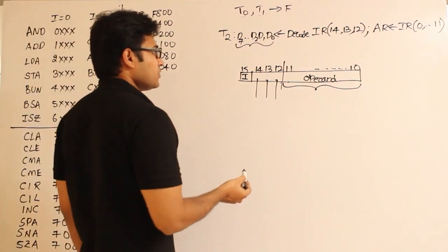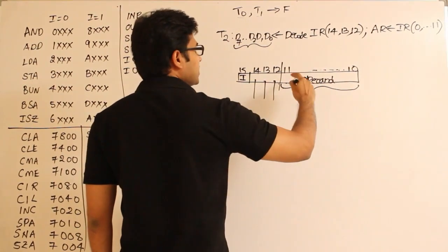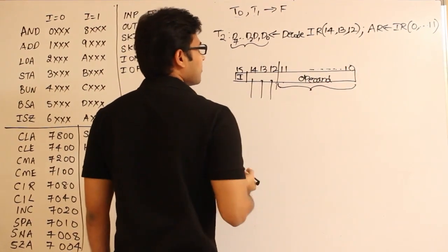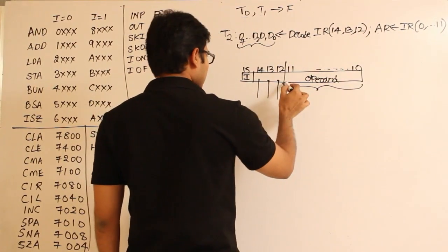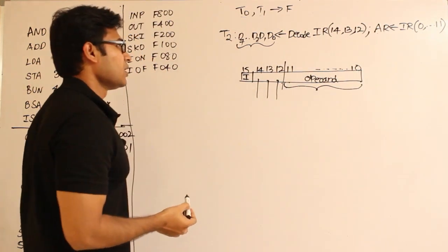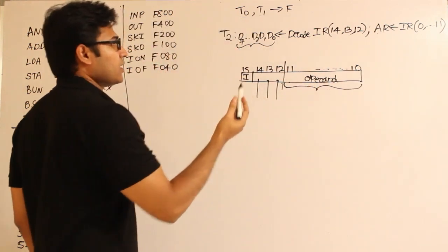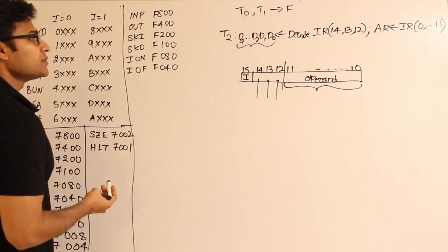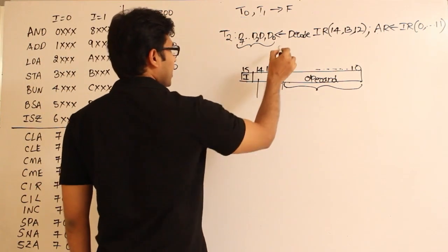You know what, when you select this IR, all these 16 bits will be placed onto the bus, but then since address register is just 12 bit, it will read the least significant 12 bits and it will ignore the remaining bits. Therefore, by doing this, what we are trying to send is the actual address, only the address part, and we are going to have a special flag.